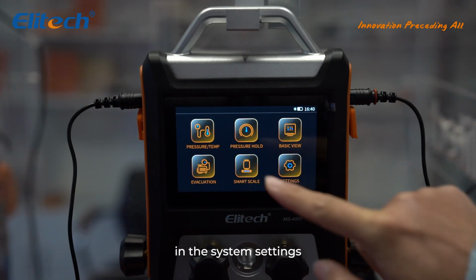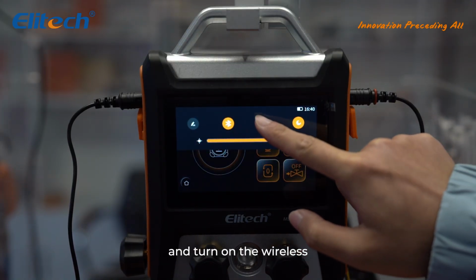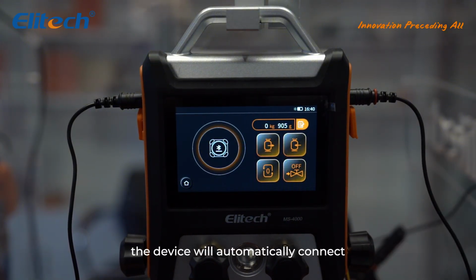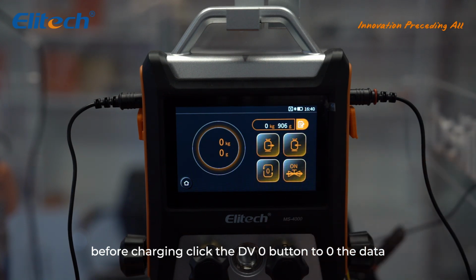Refrigerant charging. In the system settings, turn on Bluetooth and the refrigerant scale switch at the same time, and turn on the wireless switch of the refrigerant scale. The device will automatically connect. After a successful connection, the refrigerant scale icon will be displayed in the status bar. Before charging, click the 0 button to zero the data.